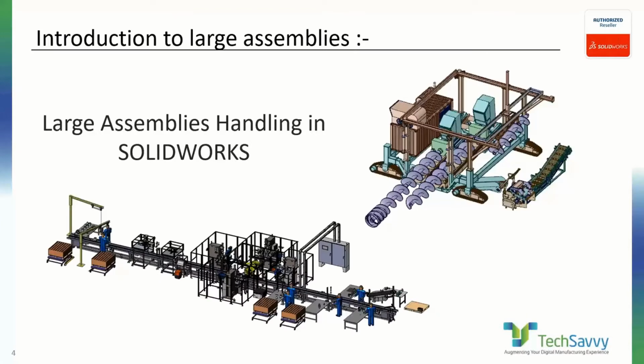As your assemblies grow larger, they will consume more resources. Your system must load more geometry, solve more functions, and display more data. This can lead to slower assemblies and drawings. You can minimize the additional overhead by building your assembly more efficiently and by using SolidWorks features. They are designed to optimize workflow within large data sets.